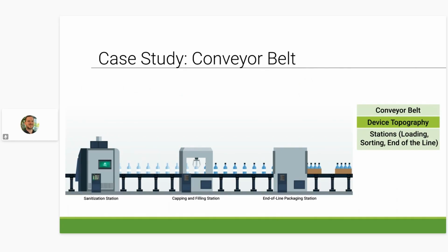Conveyor belt systems are a big part of many industrial automation applications, especially in online shopping facilities, food and beverage industries, but also as part of any industry that deals with assembly on a day-to-day basis. Conveyor belts make an assembly line seamless and efficient. However, many conveyor belts could stretch across an entire facility, making the use of just local I/O not the most efficient. This is where the remote I/O implementation comes in. As we have discussed, local I/O can only stretch so far across a facility before it starts to become cumbersome and latent due to long and complicated wiring schemes.